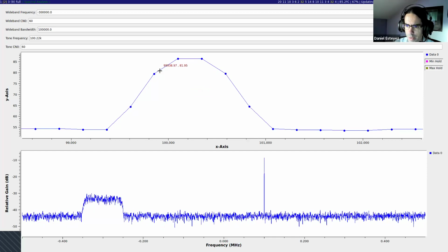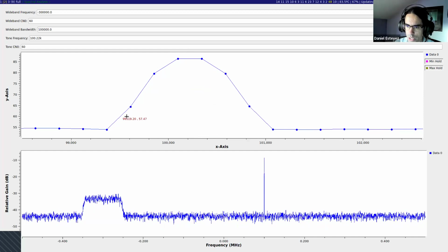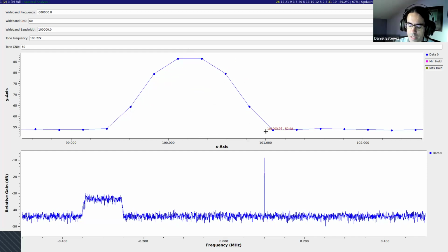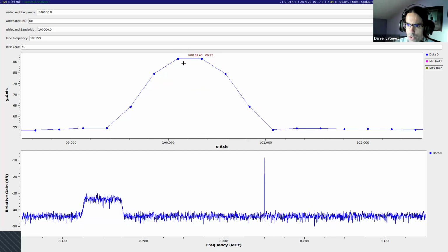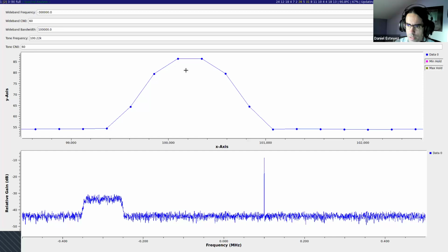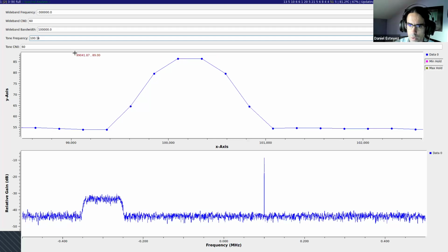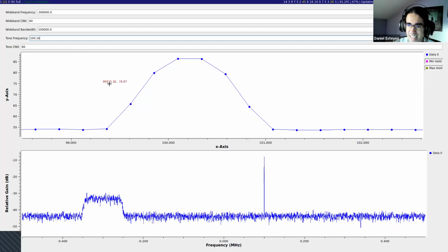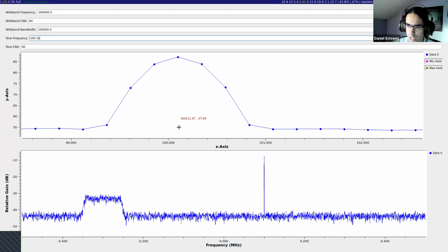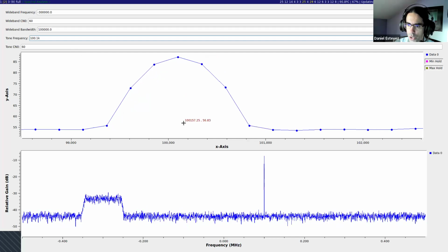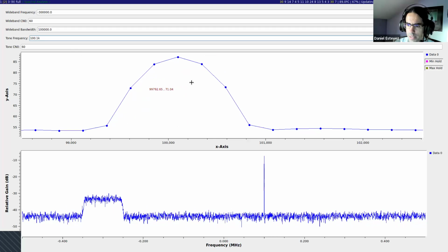The other one is the leakage. So basically my signal is here, but I also see some signal power in there. That is because of the FFT leakage. It's not possible to design an FFT window so that the signal appears only in these two bins, or only in one bin. Well, when it's exactly perfectly lined up, there is a way to have a window which only shows the signal here, and I will show you how in a second. But if the signal is not exactly lined up with the FFT bins, it's impossible.